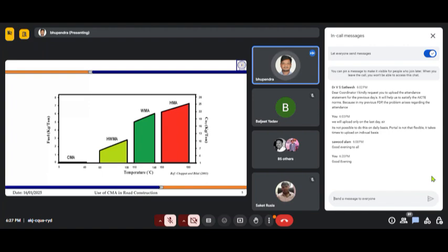And for the conventional hot mix asphalt technology, the production temperature is 150 to 190. And here the fuel consumption is 6.3, 6.4 kg per ton to 7.2, and the CO2 emission goes up to 25.4 or 25.5 kg per ton.